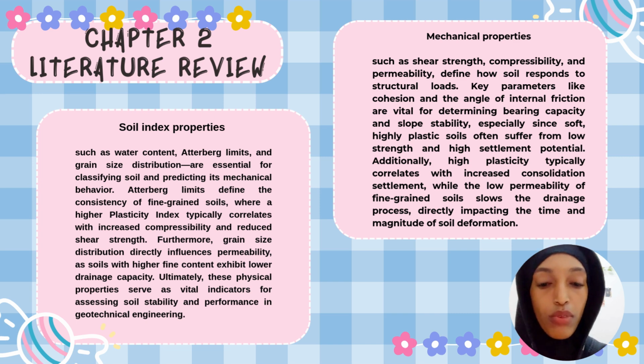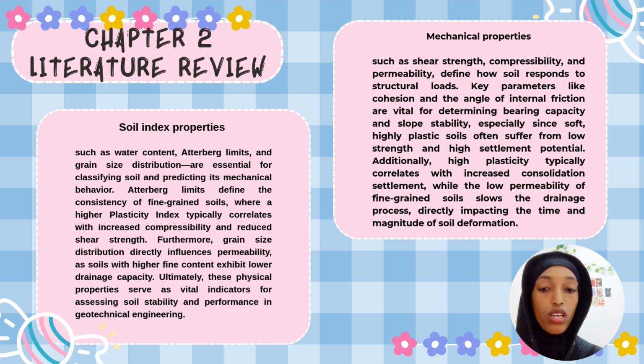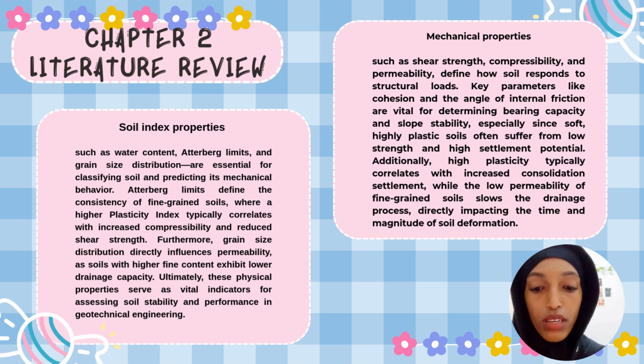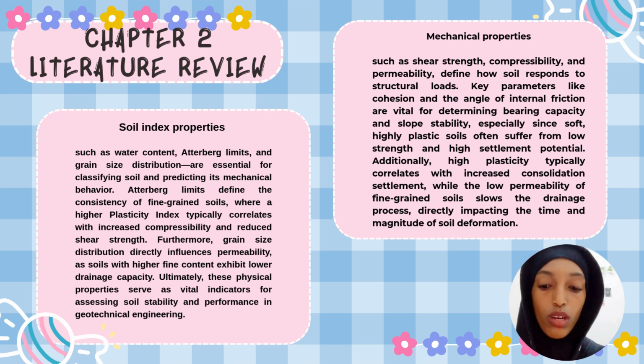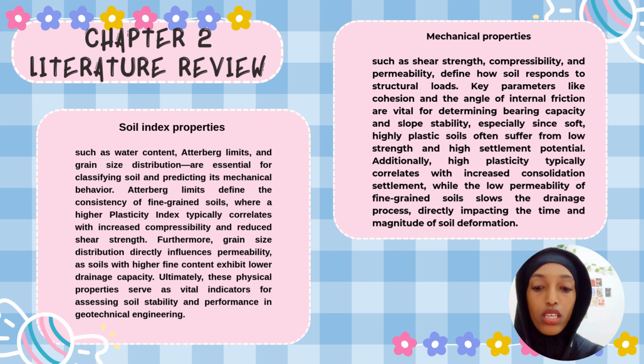Shear strength parameters include cohesion, angle of internal friction, and undrained shear strength. Soil permeability is influenced by soil composition and particle size. Fine-grained soils typically exhibit low permeability, resulting in slower consolidation processes. This behavior is especially important in clay soils.